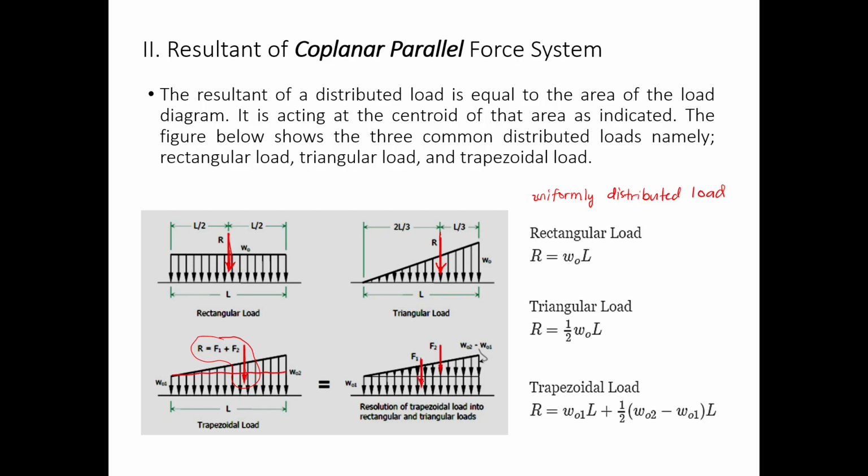One force is at the center, and the second force is at the 1/3 of the triangle, and then you take moment at a certain point to get the resultant of your force. What's important here is that you know how to locate the resultant force of your coplanar parallel force system.